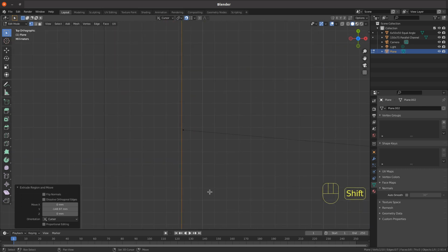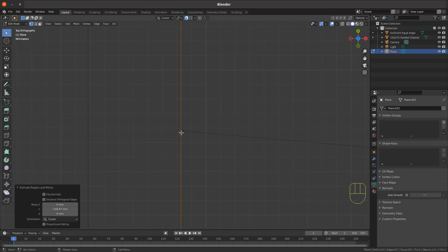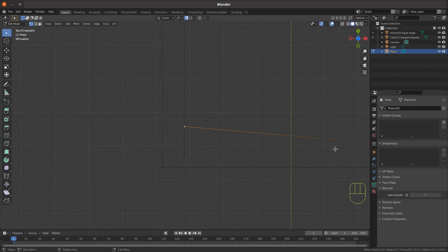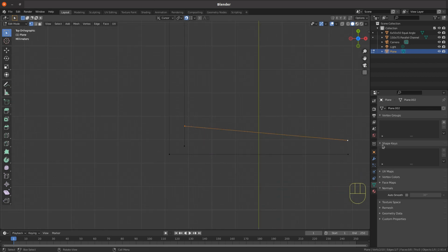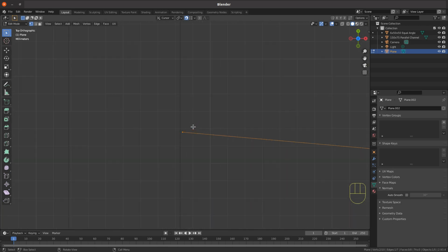You'll see that the angled edge has been rotated out of position with regards to the web, or what will be the web. So we need to be able to extend this edge that's angled to form the inner face of the channel's flange.